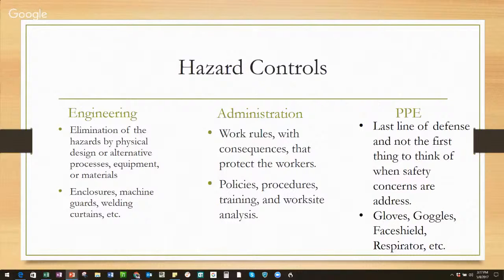And the PPE is the last line of defense, unfortunately; most people go to PPE first. If I told somebody who's working on a roof, and the roof could accommodate guardrails and the company has the guardrails with them, then I would think that they would want to go for the guardrails first. But mostly we hear, let's go ahead and throw on that personal fall arrest system, find our anchor point or lifeline, and then let's do it that way.